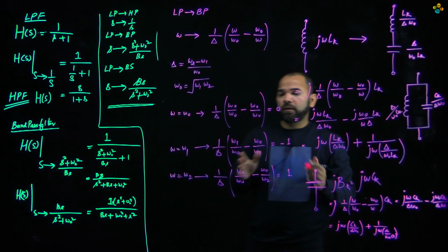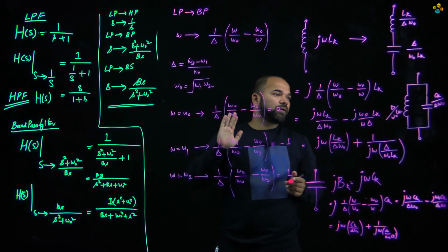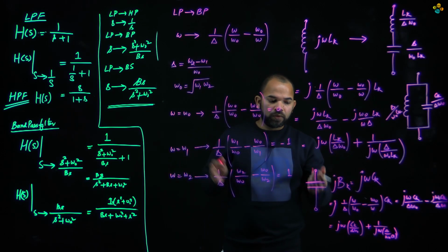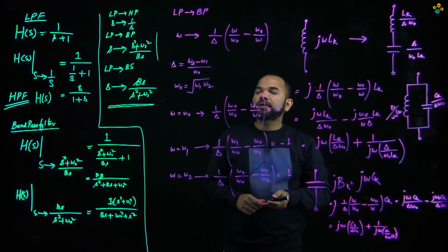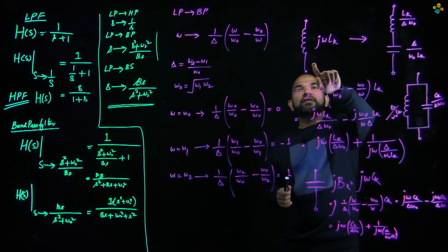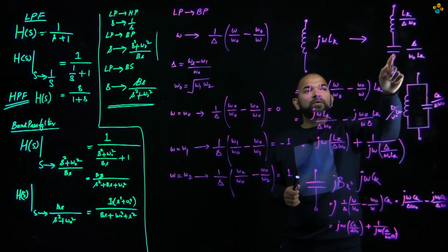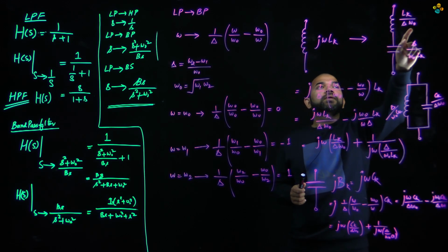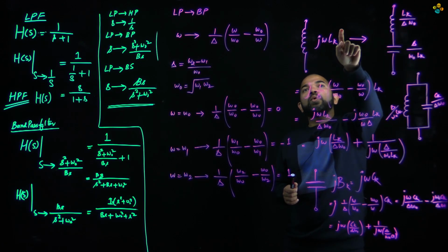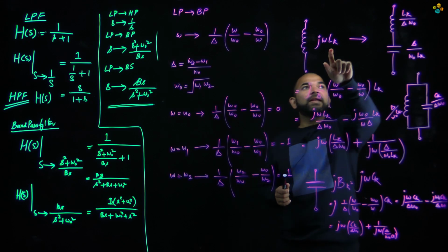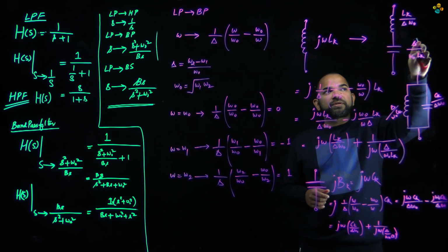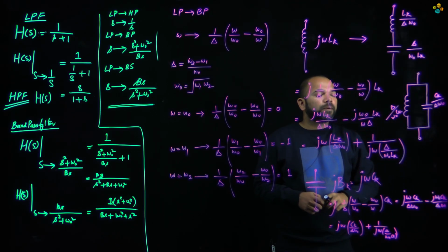Now if we want to change a low pass filter to a band pass filter, we need to first design the low pass filter and calculate all the values of the low pass filter. Then every inductor is going to be replaced with a series inductor and capacitor, and the values of the new inductance and capacitance are calculated from the original g values, in terms of Lk and a few other parameters like del, which is basically the frequency parameter.